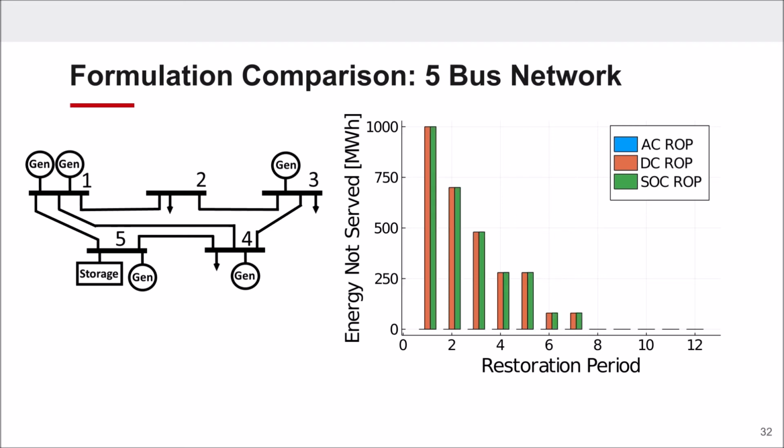We bring in the second order cone version or solution in the green here. And you can see that it actually came back with the same solution. There's barely any percent error representing the losses in the network, but it's effectively the same ordering sequence that it solved with. This isn't a guarantee by any means with these two different power flows, but in this sort of a case of every device being damaged and such a small network, it's not entirely unexpected.